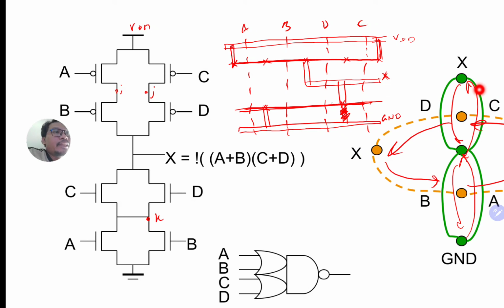The other part of the C is connected to everything. Okay, so here is going to be something like this. Okay, so here you have to jump metal, so that we don't short it. Okay, something like this. Okay, so now we can see that one part of A is connected to BD and also connected to one part of the C. Okay, so this is the so-called stick diagram,